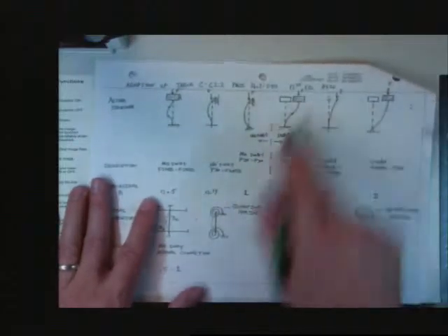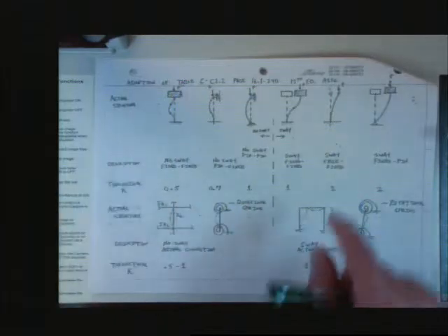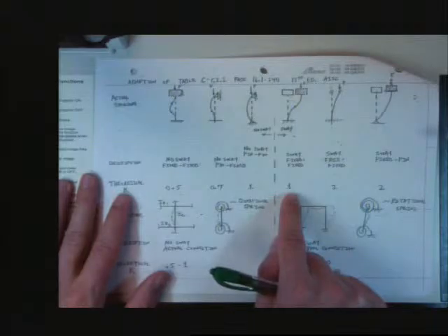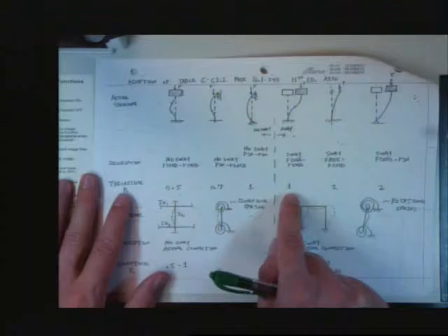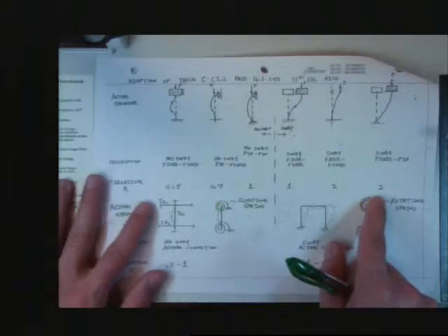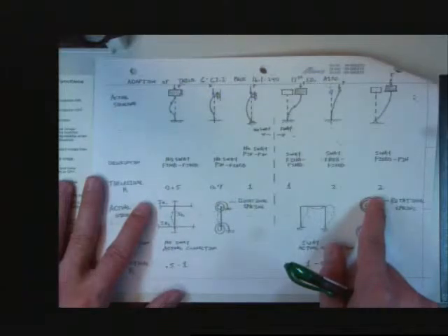So these would be sway structures. These would be non-sway structures. So if I have a sway structure, my K can never, ever get better than 1. What's the worst it can possibly be? Infinity. What's the capacity with a K of infinity? 0. How'd you know? Go back to the table.